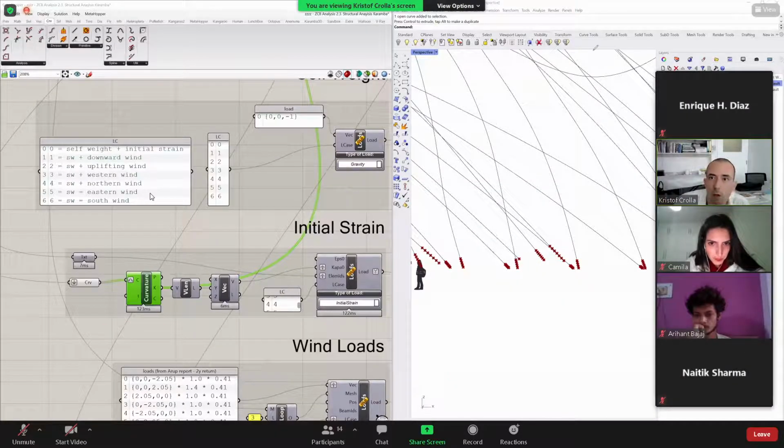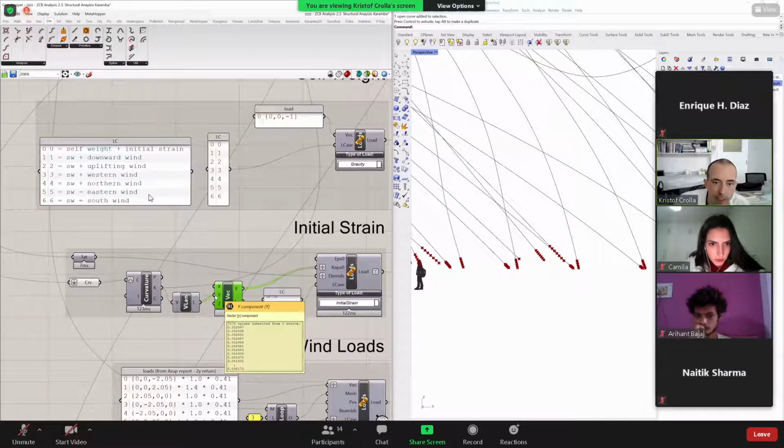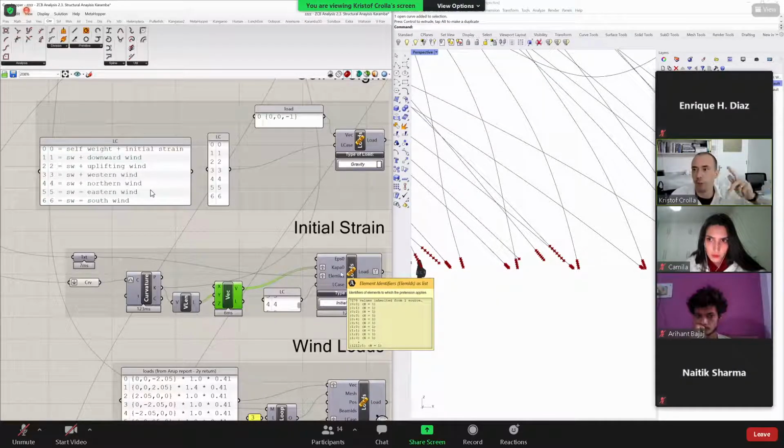So then all we need to do is, yeah, get the length of that vector, because the orientation doesn't really matter. And then we're turning that just into a Y vector with that same value, because the orientation of this curvature is done relative to the XYZ coordinate of the elements themselves. So each element that's brought in has its own orientation inside the Karamba calculation.